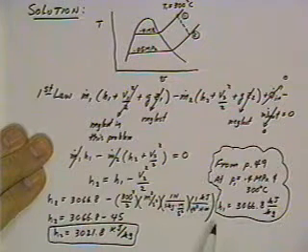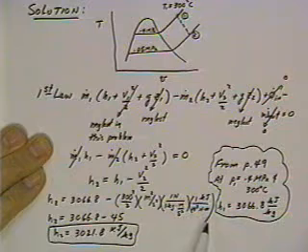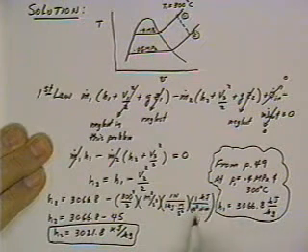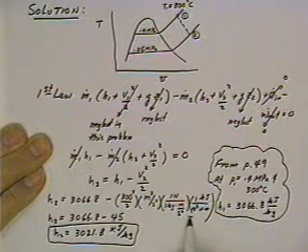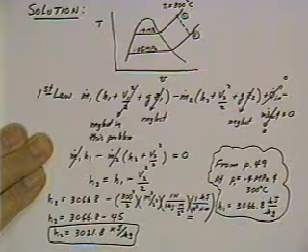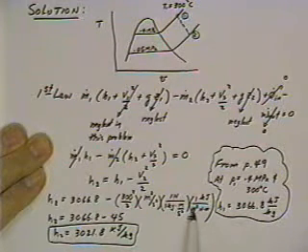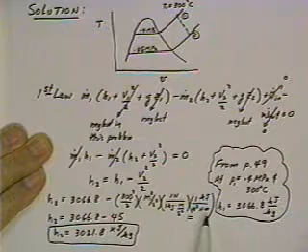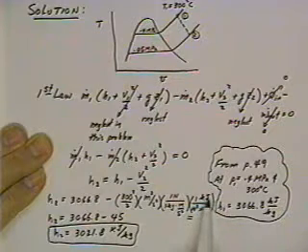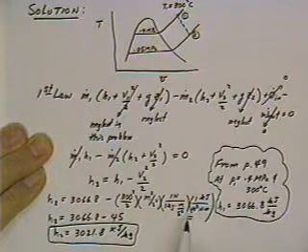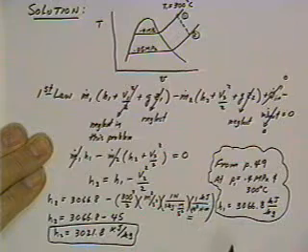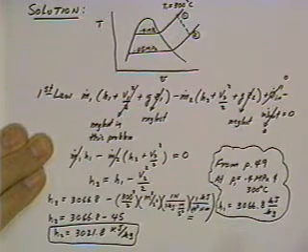So when you plug in all those units, cancel them out, making sure your units are compatible. And this is real important to remember, since you've got your answer in kilojoules, this 10 to the third Newton meter per kilojoule conversion. Otherwise you get huge answers that are in error by a factor of 1,000.